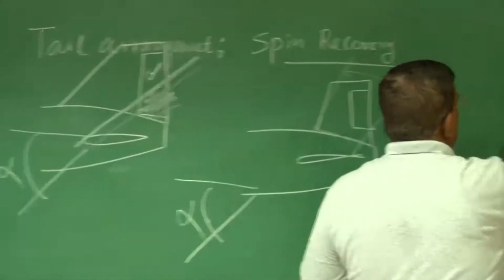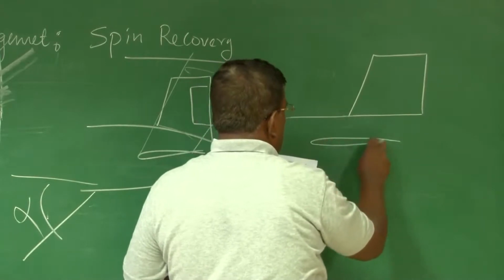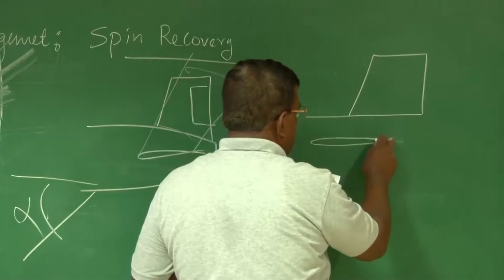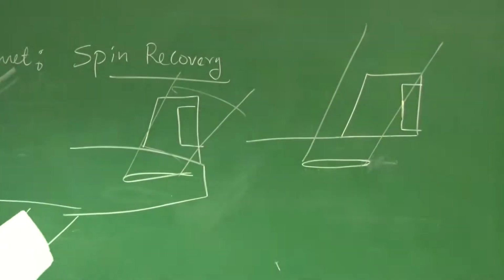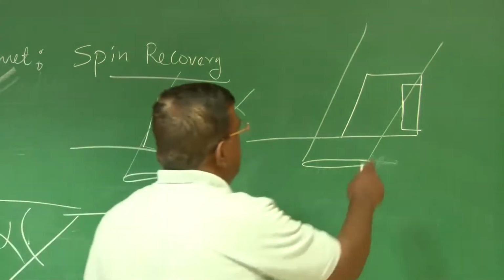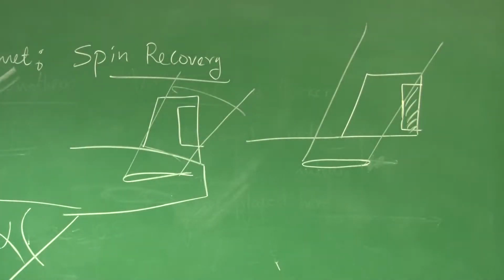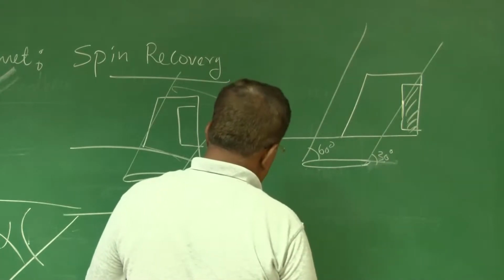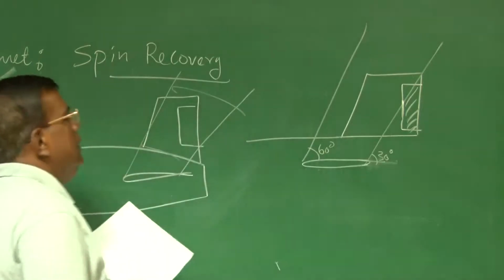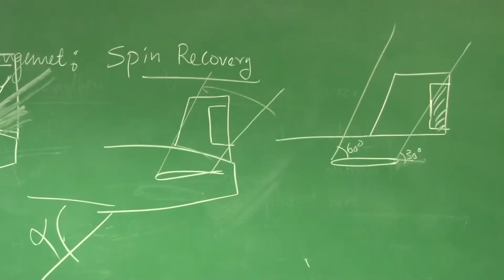So what is done generally is, it is better that you put the rudder here, fine, and then take the horizontal tail a little ahead of this. So what will happen if you take it like this? A major part of the rudder will be least affected because this much will not be affected. So you have enough rudder power. What is done is, generally you draw, these are all empirical, around 60 degrees here, around 30 degrees here. This is again from Raymer. And see, by placing the location of the rudder and all, how much area is getting blanketed or coming into the wake. If 75% of your rudder is out of the wake, you should be happy.